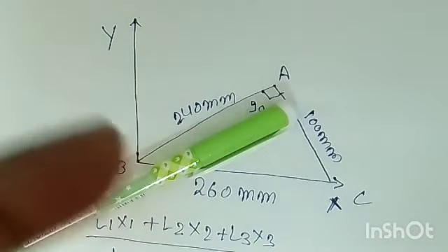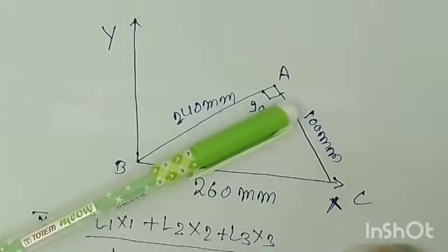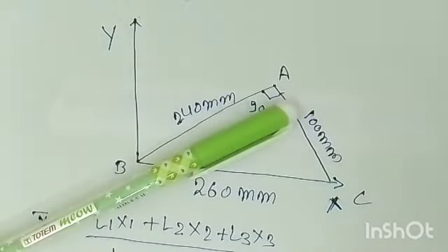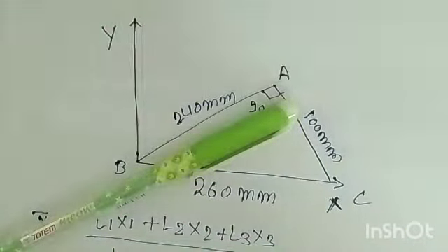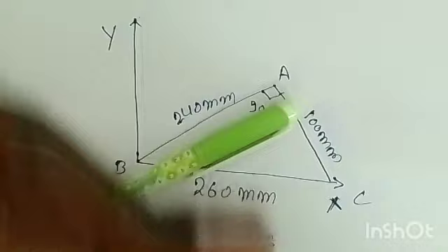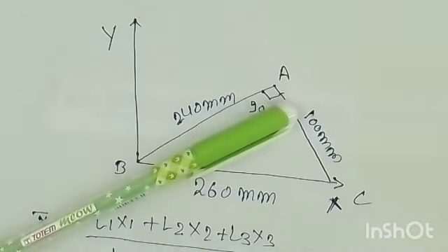The x center of gravity is nothing but half of the length of the horizontal component of AC, right? And similarly for the y axis, half of the vertical component of AC. So first of all you need to find the components of AB and AC. Why? Because AB and AC are inclined. We need not do anything with BC, okay? Why? Because BC is exactly vertical, right?